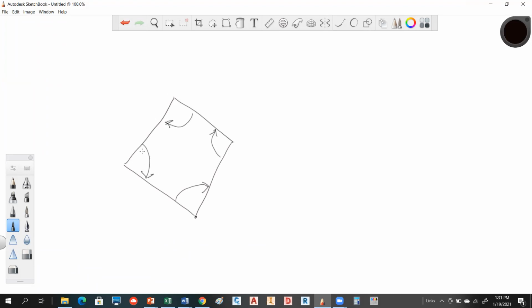That's pretty important. There's nothing that says you have to, but if you don't, then you screw people up in the field. So a lot of people turn what we call angles to the right. These are indicating angles to the right. So these are called interior angles. So if you have a figure like this, which is not a closed polygon, notice, okay, those aren't considered interior angles because I don't know whether I'm interior or exterior. So there's a big advantage to using this type of angle.